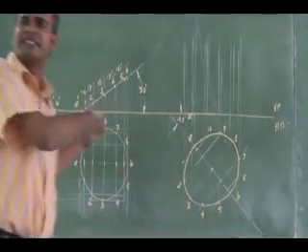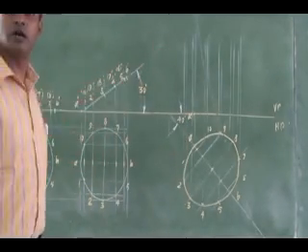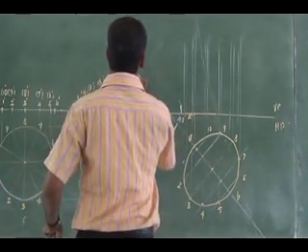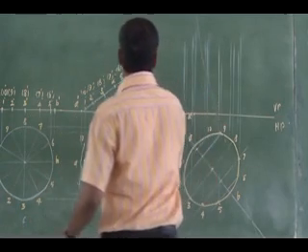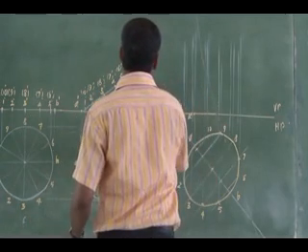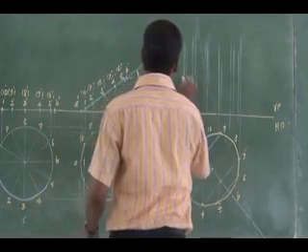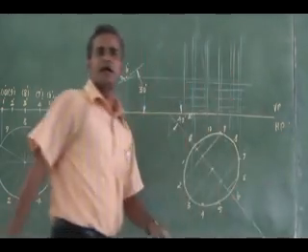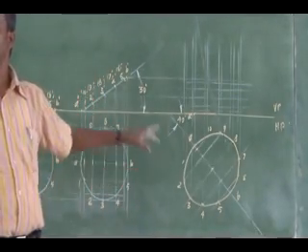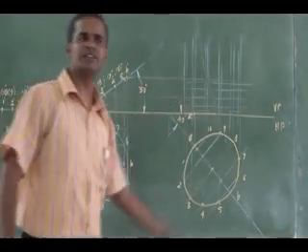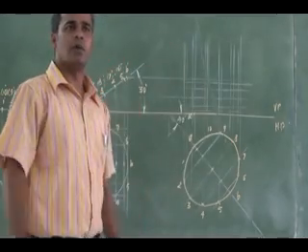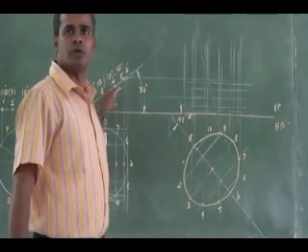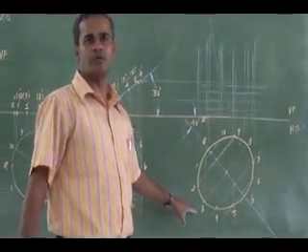Then from the previous top view, you draw horizontal projectors, and from the previous front view, you extend horizontal projectors. Carefully you see, you extend horizontal projectors and vertical projectors from the points. This is from the previous front view, and this is from the top view, right?